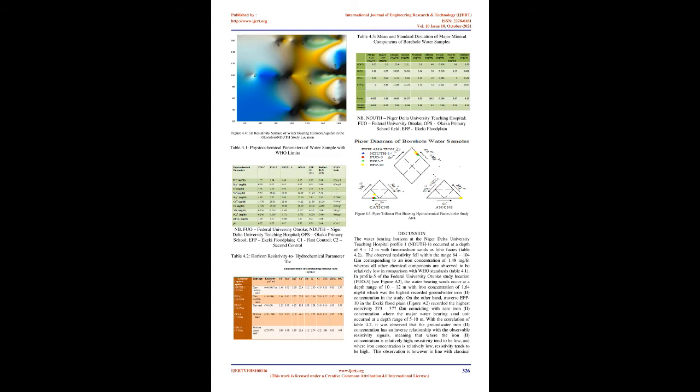Also, resistivity surfaces corresponding to aquifer horizons were extracted from the geoelectrical data to produce a three-dimensional view of the electrical behavior of the aquifers under investigation with resistivity as the third dimension. The structural closures of the resistivity highs constitute possible targets in line with mathematical relations highlighted in [21]. B. Lithologic logging / physicochemical analysis.